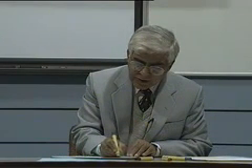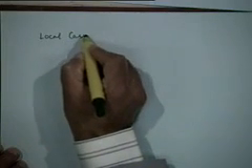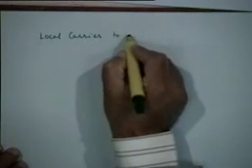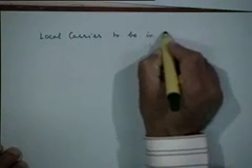So therefore this gives you an alternative method for demodulating SSB signals. Now that issue that was raised a couple of minutes ago, about the phase coherence of the local carrier in this case, right? It's true. Even in this situation we would require the local carrier to be in phase and frequency synchronism.